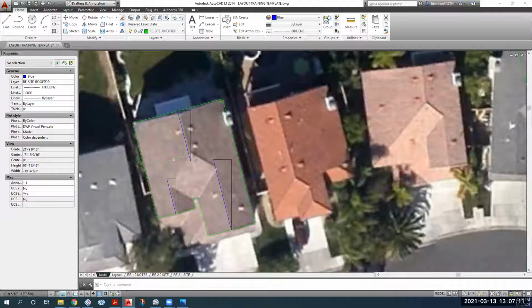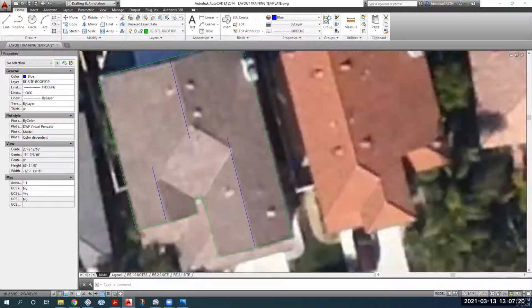But before that, let me tell you guys how to rotate a line to align it 45 degrees from there. I know that this valley is going to start from this corner on this roof. So I'll make a line here, and it's fine if I work in ortho mode and that line is perpendicular. Can you tell me how much this line needs to be rotated so that it is 45 degrees from here? Will that be plus 45 or minus 45?